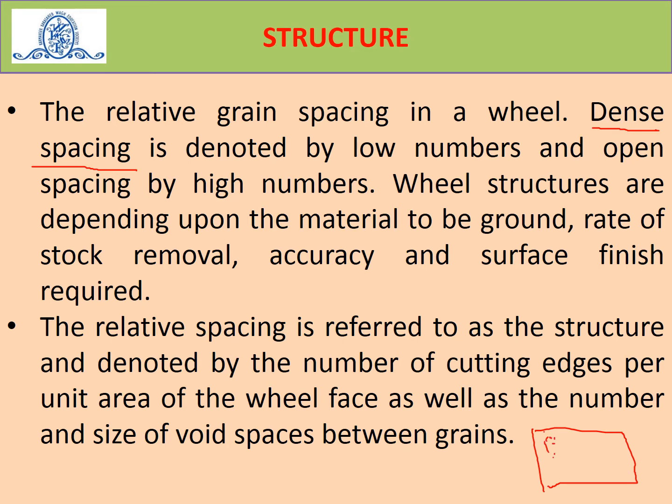If the cutting elements are very close to each other, then we call it dense spaced. And if the space between two elements or two particles of the grinding wheel is large, then we denote it by a high number. Wheel structures depend upon the material.